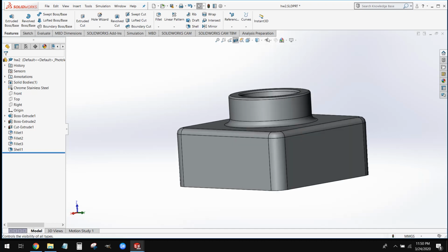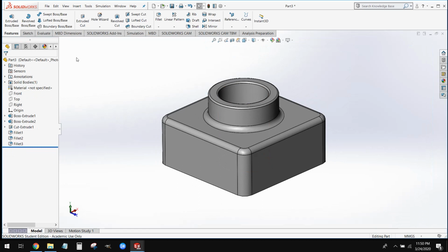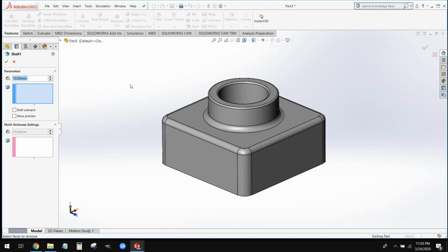To do this to our piece, we're going to use the shelling tool. That's located underneath our Features tab, towards the end of the toolbar. This tool applies pretty simply. What we're going to do here is we're going to set our shell thickness. This is how thick our candy coating is on that M&M. We're going to set this to 2 millimeters.